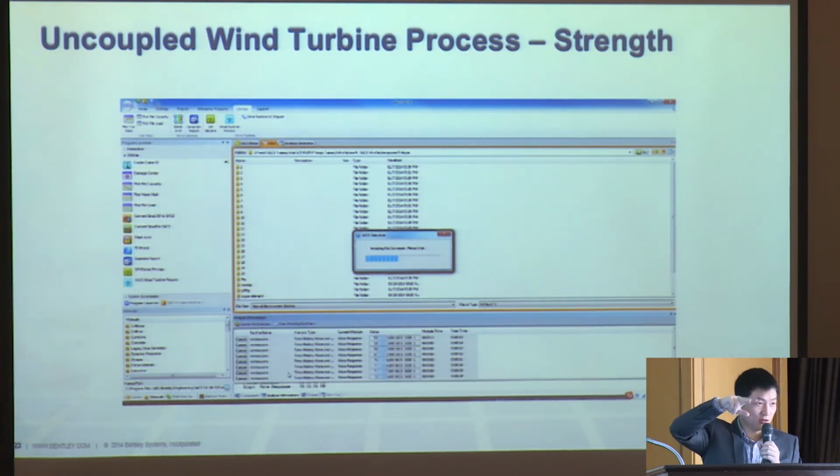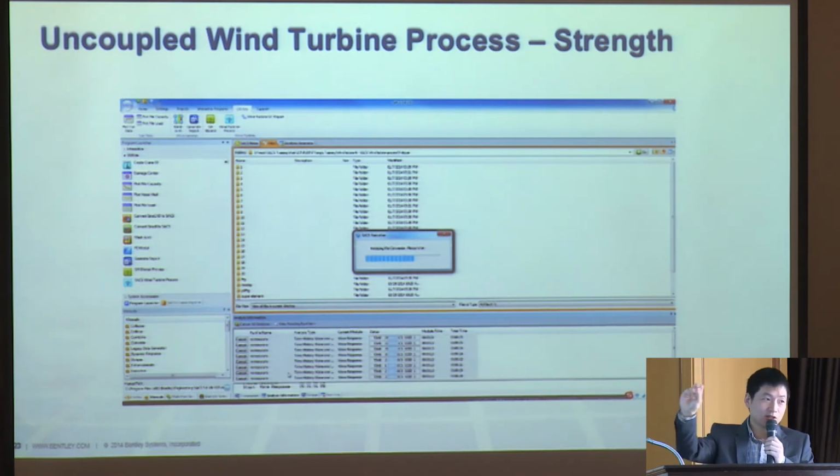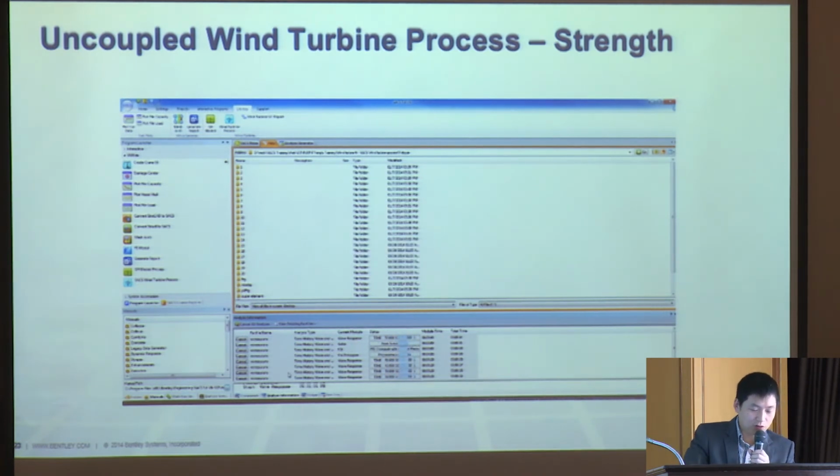For the stress cycles and the number of occurrences for each stress range, we use the rainflow counting method. For a time history simulation, we always get the cycle stress and the number of occurrences by the rainflow counting method.